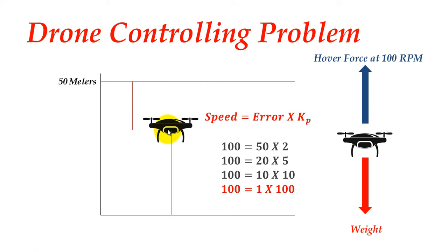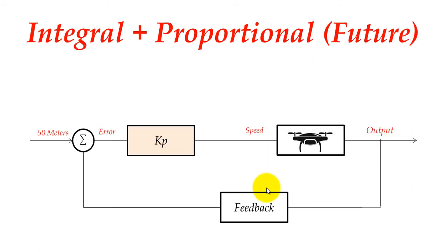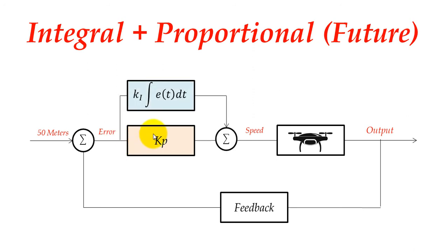So in many applications, when using proportional controllers, we will not remove what we call a steady state error. The problem now is we want to eliminate the steady state error. So imagine that we have added to our control design what we call an integral controller. And the integral controller actually takes the error and integrates it over time to provide a control action.